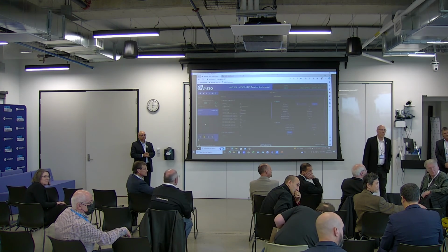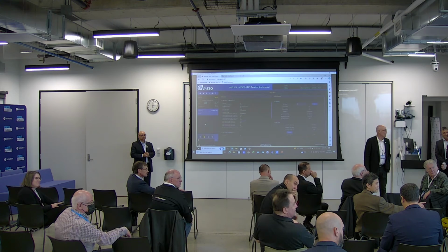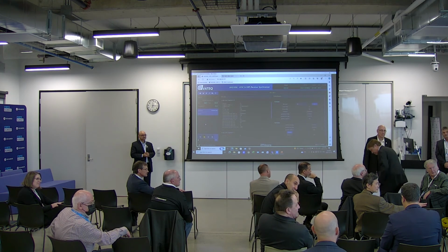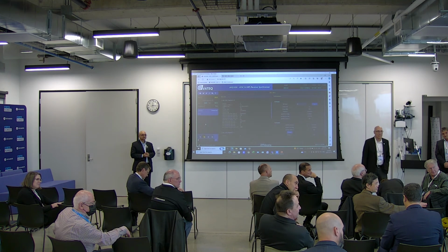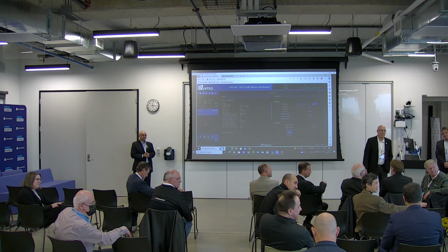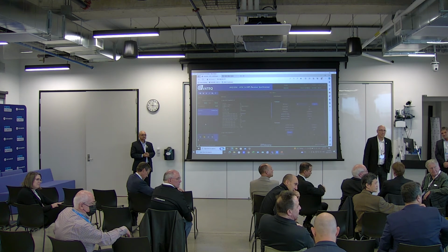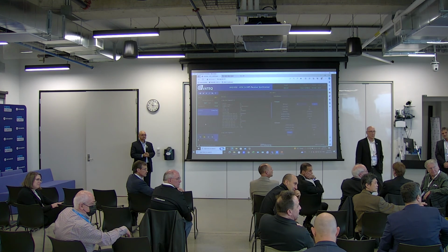So when people talk about 10 meters and you mentioned 3 meters, the industry standard and what we expect for GNSS today, last year, and the years to come is about 2 centimeters. So it's about an inch, 1 sigma horizontal.